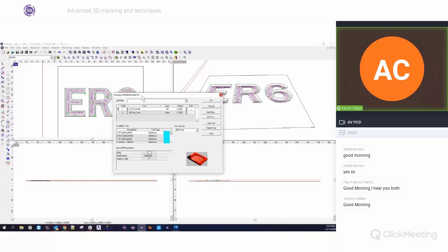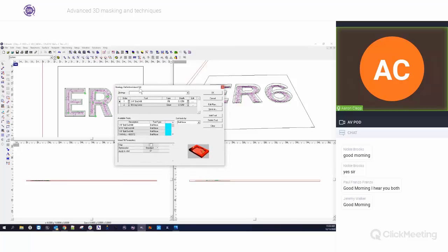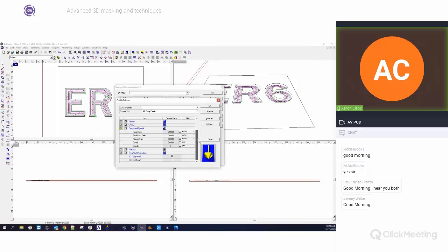So when I set up an island fill, if I set a 1/4 inch end mill first, this is going to hog out the center of the letter. And then I went in here and I selected my 90-degree conic and I told it to be a clean toolpath. But here's where we added one little step. I clicked in here, and under the 90-degree conic, I chose 3D toolpath.